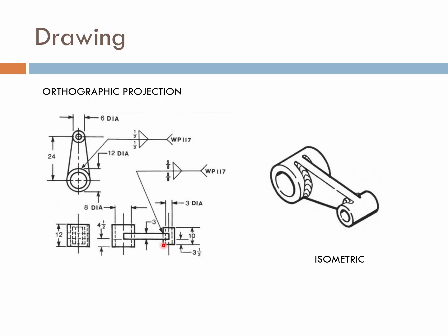Okay, and then we'll get into these welding symbols, and this tells you that this is a fillet weld, both sides 1/2 inch. This is a fillet weld 5/8 on both sides, and WP17. So these are notes, but we'll get through these later. But what we're doing now is just trying to get the basic concept of the drawing.